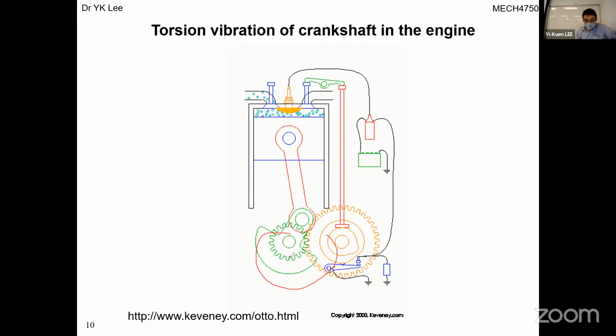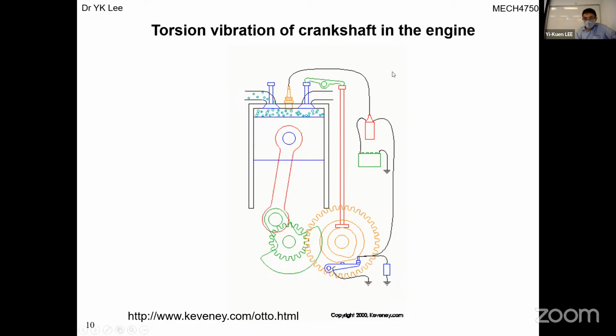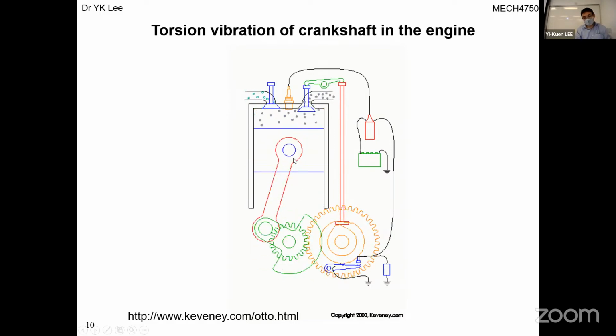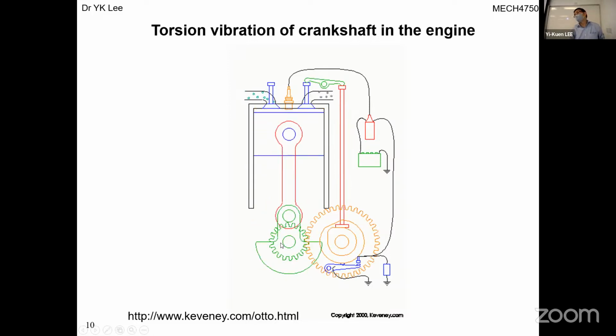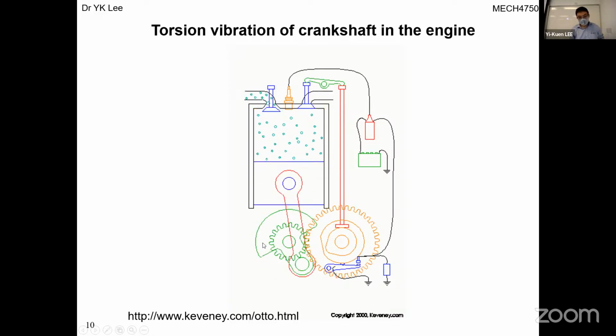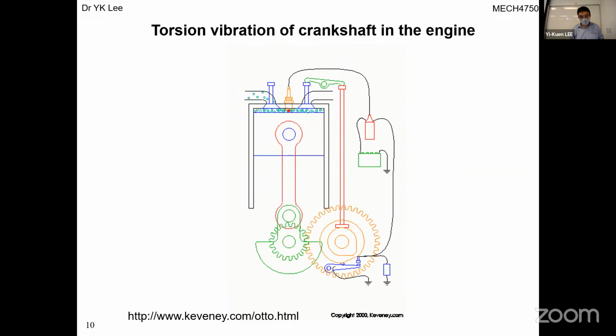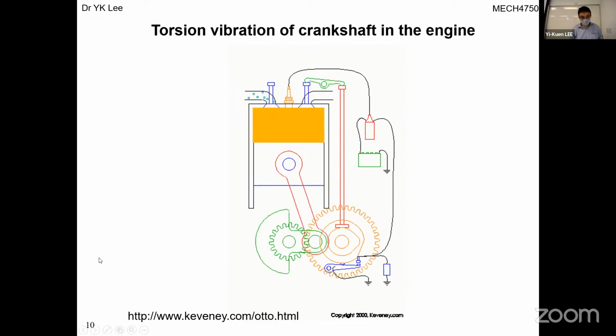We studied rotating unbalance in chapters 3 and 4, and it causes this kind of vibration problem. In this case, we may want to add an additional torsional vibration damper to minimize the stress. The harmonic force and harmonic stress will cause a reliability problem, and then this engine may fail rapidly, so reliability is a big issue for engines.